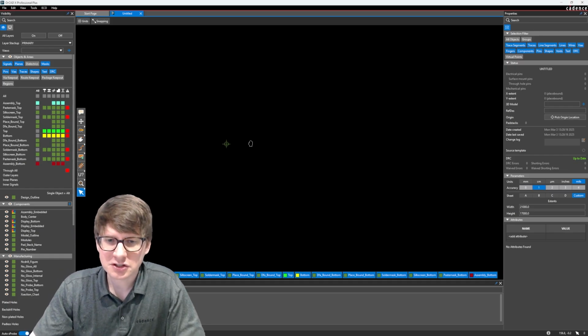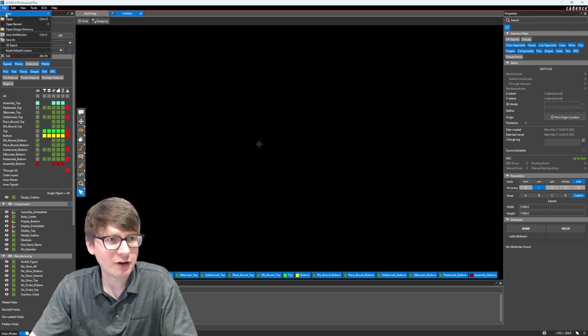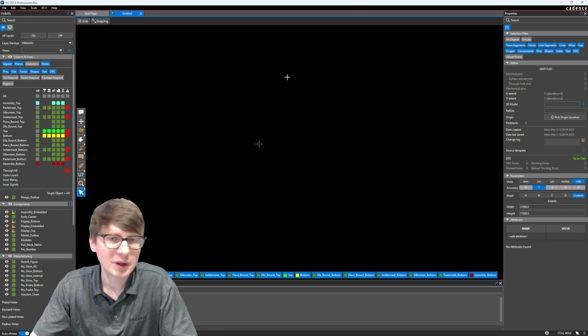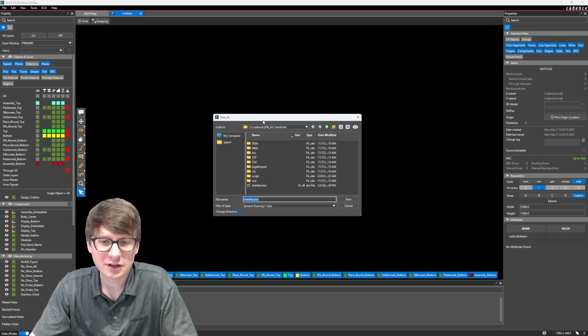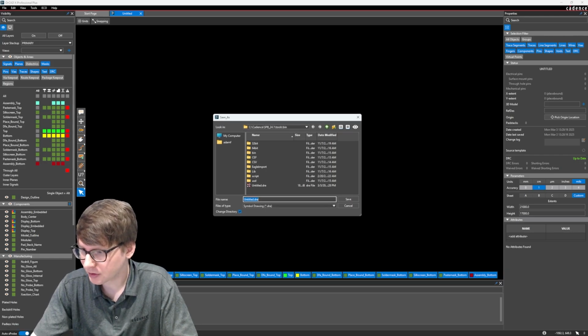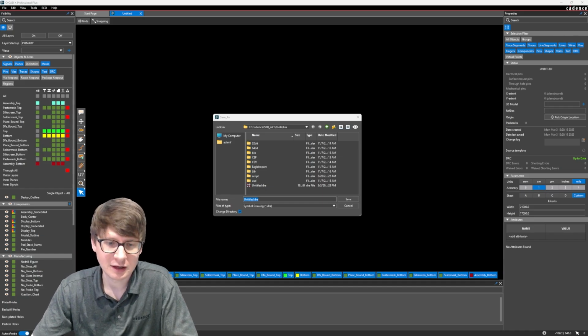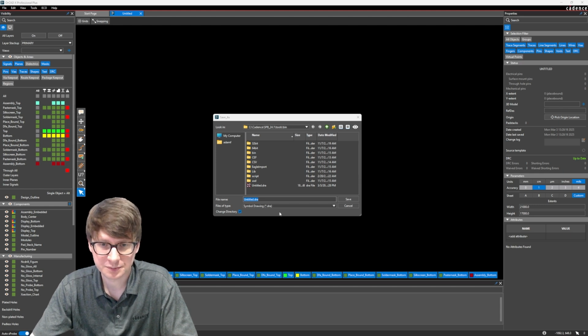All right, so let's just jump into it. To create a footprint in Presto, it's super easy. It's File, New, Footprint. And what I recommend, the first thing that you do right after you create a footprint is go to File, Save As, and save it in your workspace. Now your workspace, if you remember, is where you keep all of the required documents and symbols, footprints, etc. for the components and projects in your OrCAD X Cloud workspace.